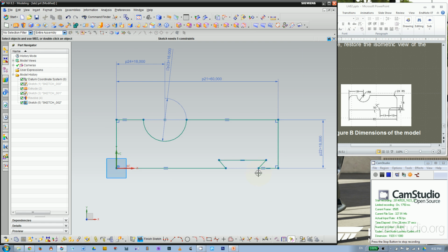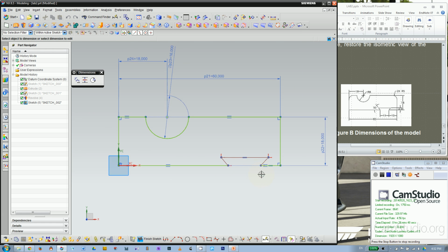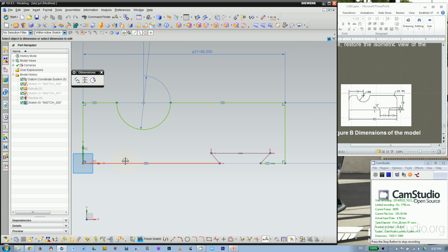And it's very simple. And for this geometry here, we can just use dimensions. And once you activate dimension, you know where you need dimensions. Those places that are green, you don't need the dimensions. So I just need 50 degrees here, and it's not there, but by default, you know it should be symmetric. So I'm gonna add another 50 here. If you don't like to see the numbers, you can put another constraint like equal angle or something like that.